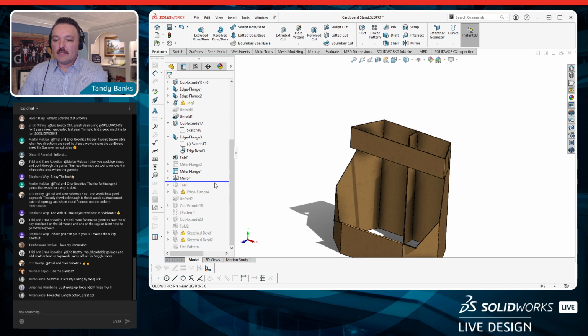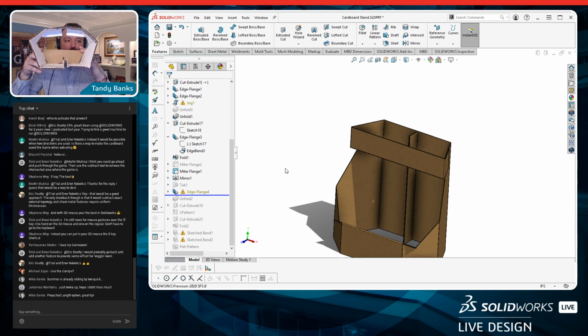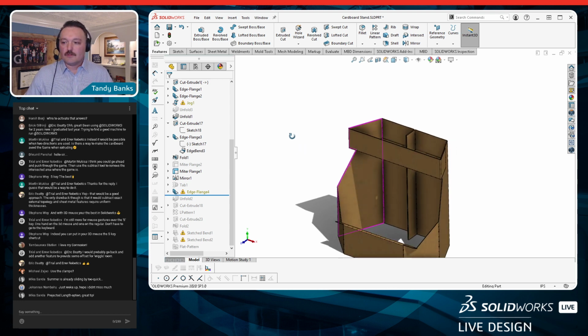The next thing was I wanted to create some structure, some stability. Inside here you can kind of see I've got a flange right here that goes through. What I wanted to do was create that fastening feature. I wanted to make some fangs that were going to stick through the wall and be able to bend down and then bend in again. That might be a little hard to see on the screen, but that's the feature I was going for, to be able to bend it in there in a couple of spots in order to make this thing assemble and attach to one another, rather than having to use glue or those kinds of things.